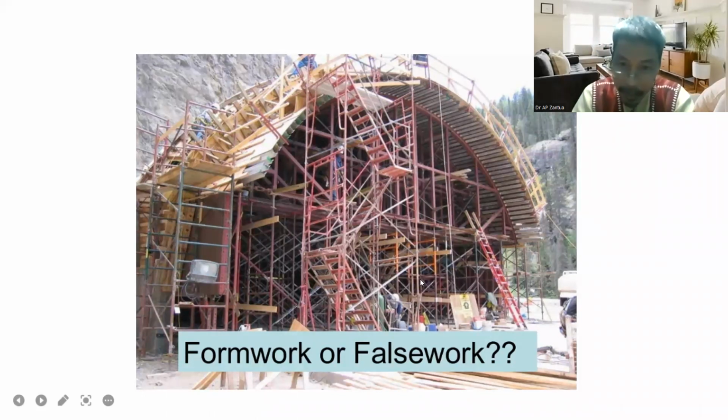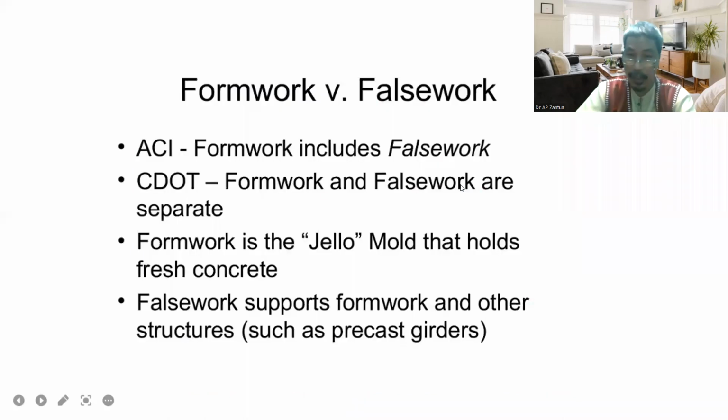And these are just falsework because they are not in direct contact, but again they are a temporary structure that will support these formworks up to the point that the structure will support itself. So that's how we can identify the difference between formworks versus falsework.